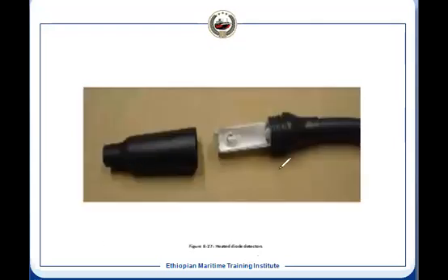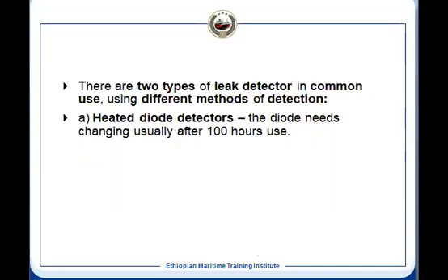What it does actually, it increases the temperature. Once it increases the temperature, it can sense the concentration of your refrigerant. It changes the resistance of the diode. And depending on that, it can detect how much it has changed and how much is the concentration, if there is any refrigerant.